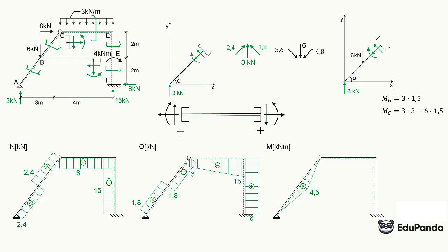So first, we will calculate the moment at point E from the point F side, not infinitesimally close. So not including yet the moment applied at point E. Then we will calculate as if considering this moment. Again, the moment at point E is caused only by this 8. The tensile force does not cause a moment. So the 8 definitely does 8 times 2, 16. This is a clockwise 16. But on this side, anti-clockwise moments are positive. So we have from 0 to minus 16.